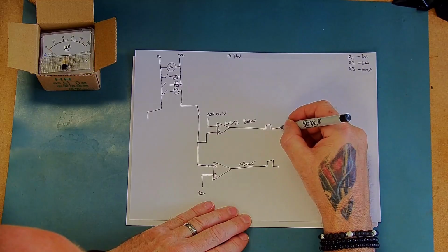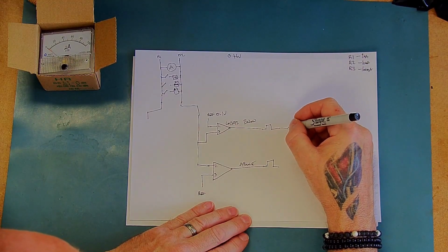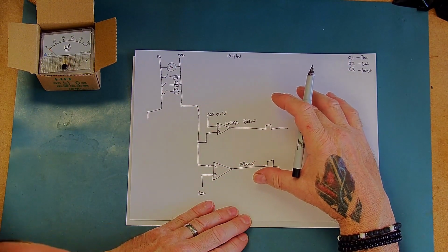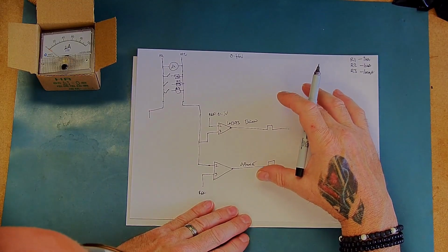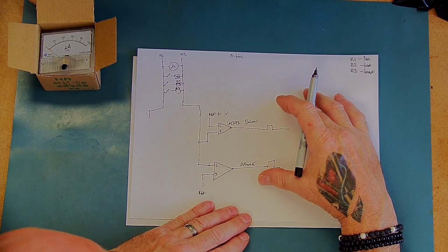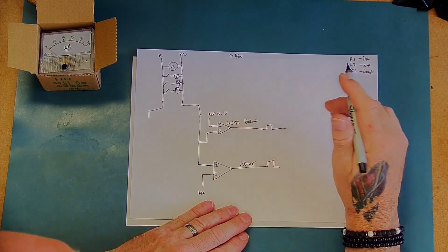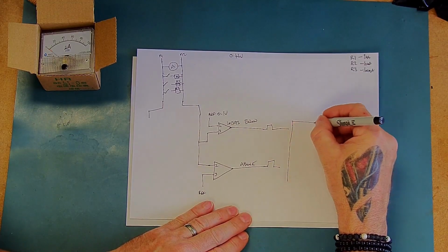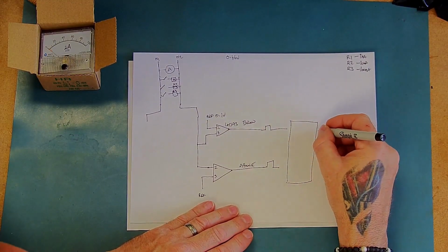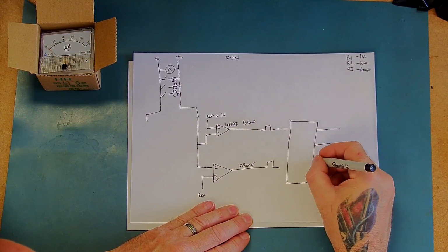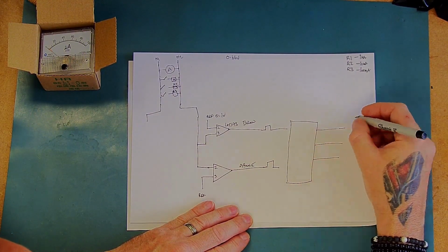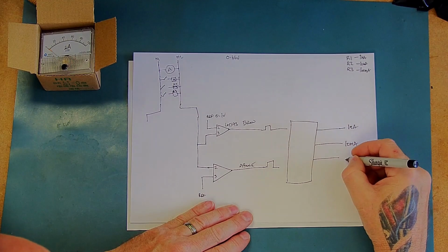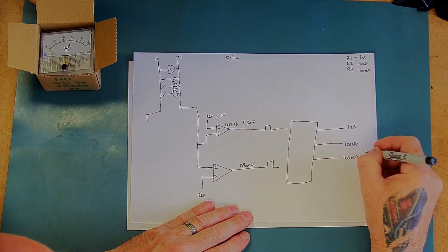So then the basic idea, and again, this is in a very simple format, we've got other things that we need to consider with this as far as our capacitor leakage tester is concerned. But fundamentally we can just say, okay, I can feed this into a controller, and the controller will have 3 outputs for my ranges: 1 milliamp, 10 milliamps and 100 milliamps.